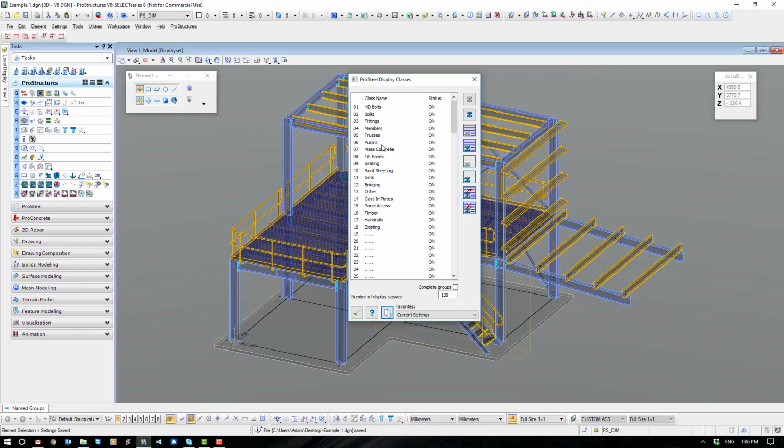So as far as procedure wise, we would select the description that we want to assign to. This button here turns the highlighted description off, this one here turns it on, and this one here assigns whatever I select to the highlighted one. So I only use 3 buttons in here. We also have the ability to toggle on, toggle off here.